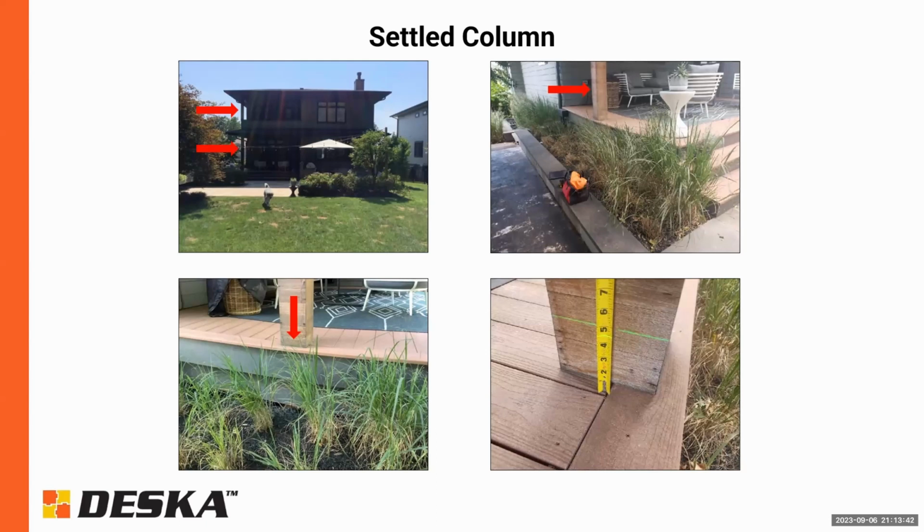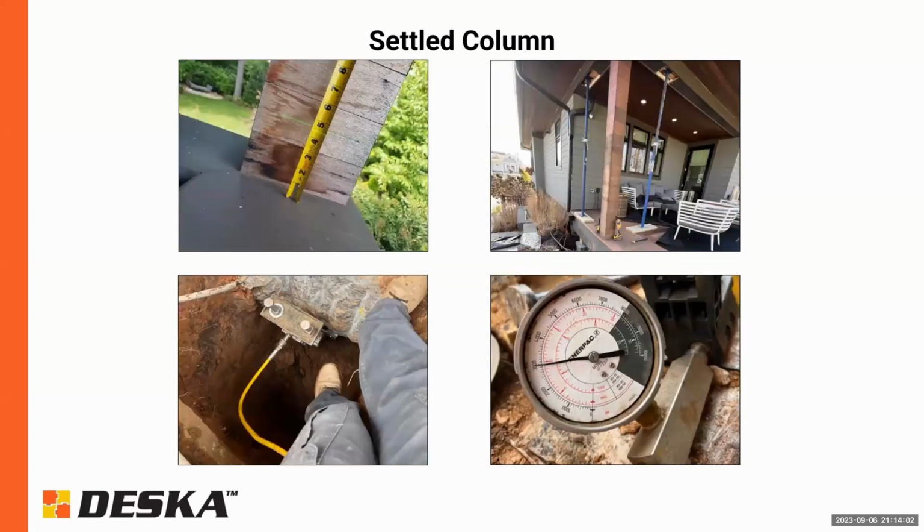And if you put a shallow foundation footing on it, it will typically settle pretty quickly. And this was only a couple years old, and it had already settled 2.5 inches, and it would have probably settled a couple inches more in a couple more years. The solution here is you have to get down below that disturbed soil.